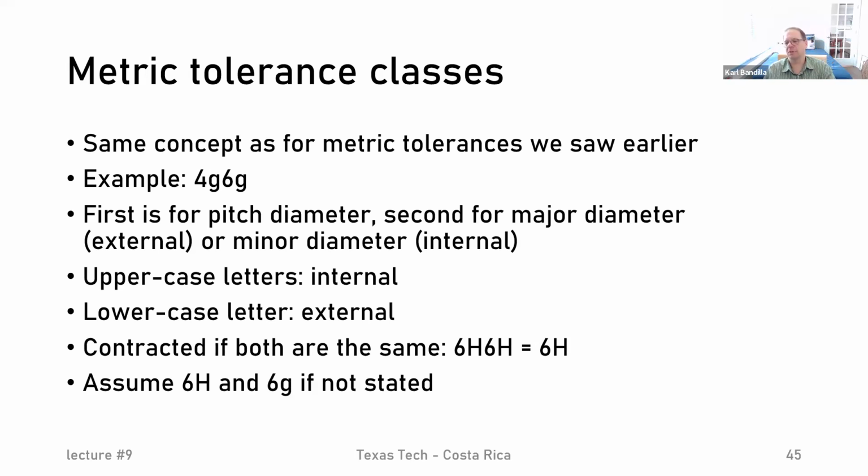So it's really impossible to get, and it would have to be a very fine caliper anyway to get between those threads. So for an external one, it is impossible to get the minor diameter, so we have to use the major diameter. That's going to be easy to measure because that's just crest to crest to crest. On the other hand, if I do the internal one, where I drill into it, I cannot measure the major one. I can only measure the minor one. That's why it's different here.